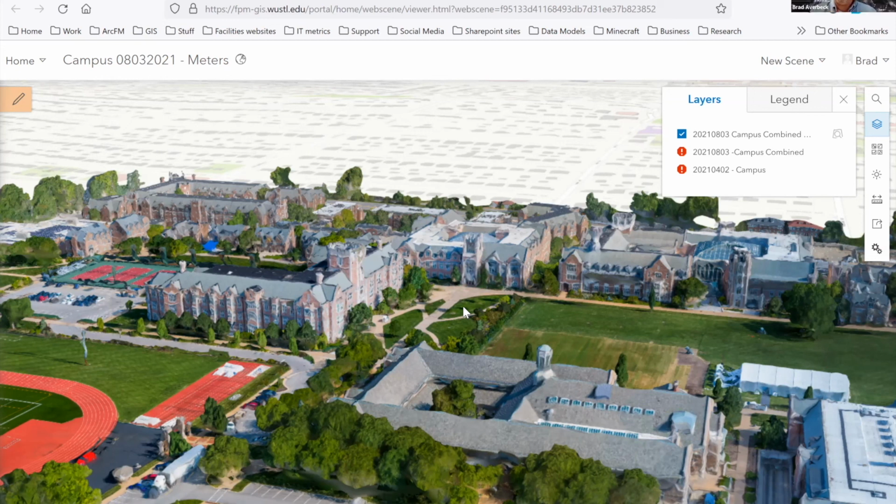So the biggest problem with measurements is snapping, right? Because you don't generally have a line to snap to. So you're trying to guess at where the beginning and the end point are. That's really the biggest deterrent to accuracy. It's not where it's at locally, the reference. Because I just did a measurement a while back because they needed to measure something on the east end of campus, and I was off by about a half foot.